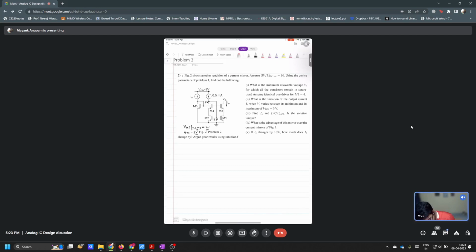So tell me, where should I bias? Now this voltage is dependent upon what? This voltage is now not controlled by these two voltages of 2 volts. So who sets these two voltages? Or even before that, who sets the voltage here, at the drain of M2? VDD.